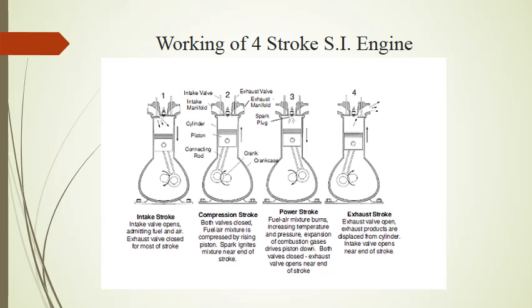Compression stroke. The fresh charge taken into the cylinder during suction stroke is compressed by the return stroke of the piston. During this stroke, both inlet and exhaust valves remain closed. The air which occupied the whole cylinder volume is now compressed into clearance volume. Just before the end of the compression stroke, the mixture is ignited with the help of an electric spark between the electrodes of the spark plug located in the combustion chamber. Burning takes place when the piston is almost at top dead center.